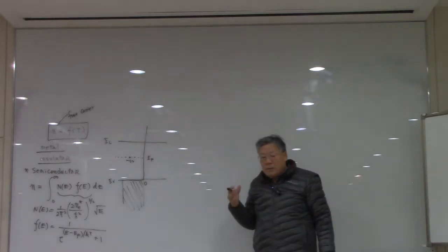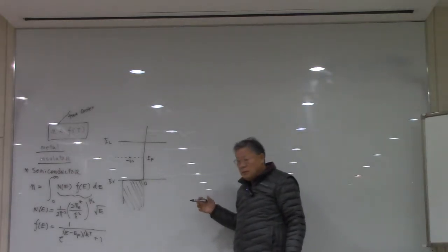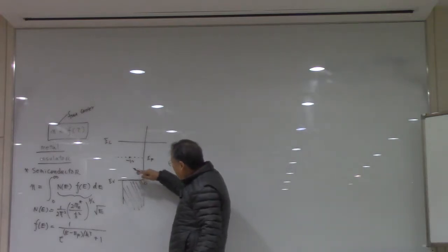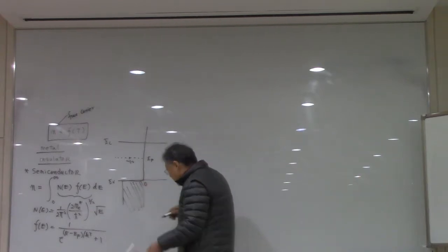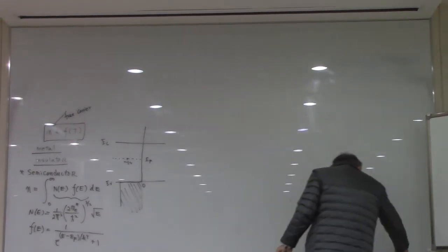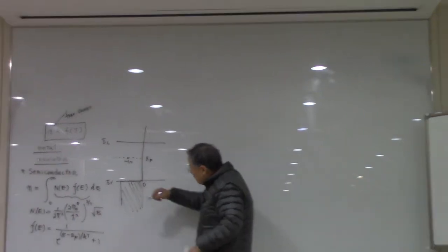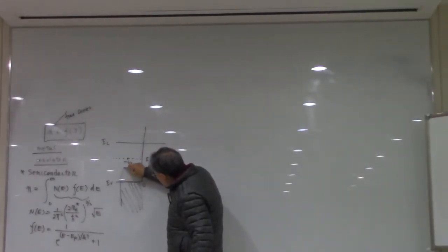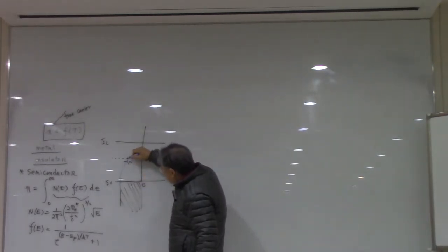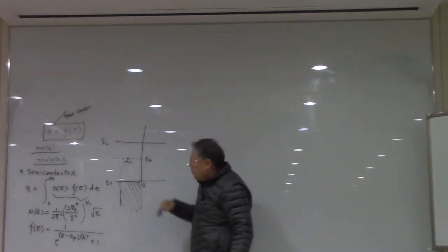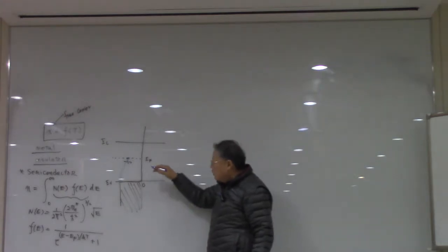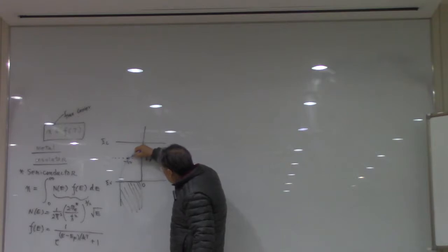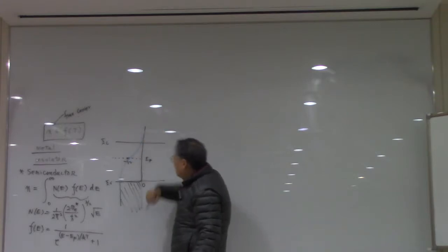But if you have an elevated temperature, more than absolute zero, then what's going to happen to this Fermi-Dirac statistics is that it is going to have a half occupancy here, then it is going down through the half to make the probability of occupancy at the Fermi energy to be 1/2. And then here it's going to go something like this.